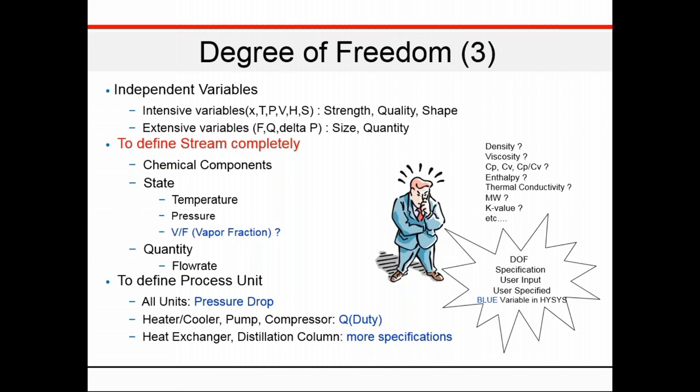In HYSYS, when we have all these values we have described, some factors will be calculated. Some of them include density, viscosity, the Cp/Cv ratio, the enthalpy changes, that's delta H, thermal conductivity, the molecular weight, the K value, that's the constant, and a couple of others too.